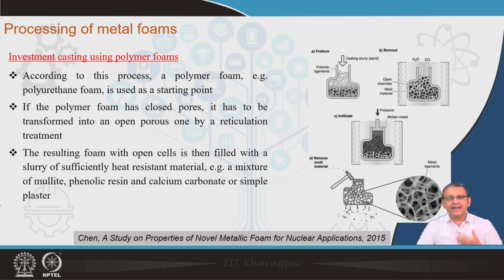The next and final step is that by mechanical force, it can be some forced water jet or some light hammering, the plasters are actually removed. That means the plasters break out and are removed, and we obtain a very nice homogeneous pore structure or metal foam structure, where the strut dimensions and the strut structure replicate the initial polymer foam dimensions and the polymer foam struts.